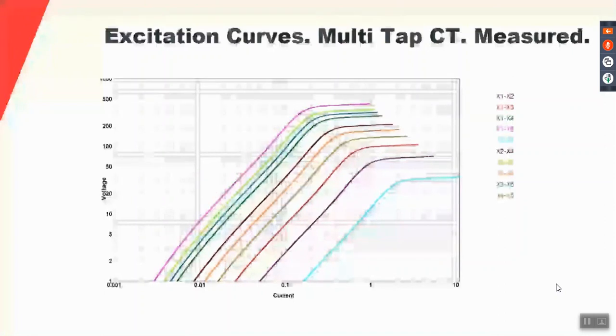on the primary, which in turn is going to become the current on the secondary, the higher the excitation current, and they have a fairly linear relationship up until the point of saturation, where everything becomes very difficult to predict, which means that when we need it the most, we have the most error.